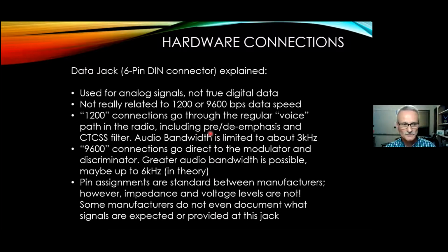increase the high frequency on the transmit side. The high frequency audio gets boosted by 3 dB per octave, and then on the receive side we go through de-emphasis. So we reduce the high frequency by 3 dB per octave, which means that we're going to bring that level back to where it should be, but we're going to be dropping the noise or the hiss down below that. So it works very similar to Dolby transmission, Dolby encoding and decoding on tape.